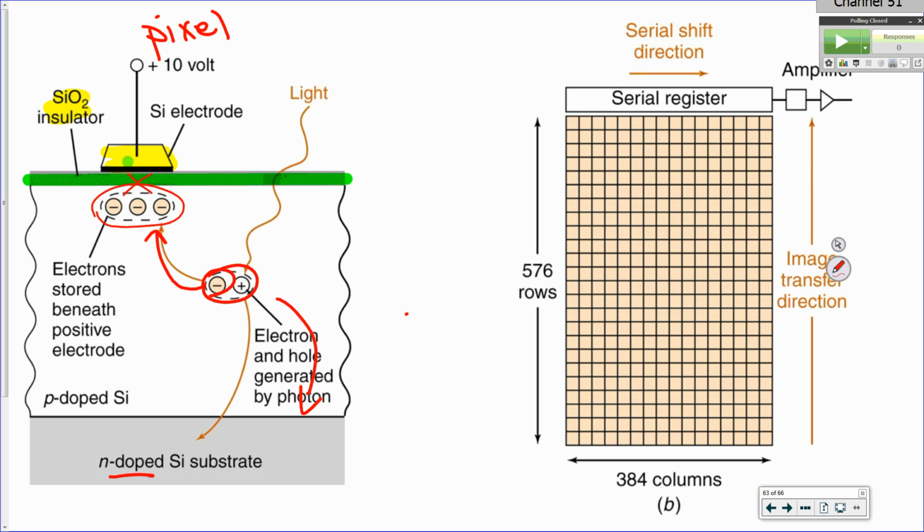All right? Or if that's not enough, if I can track good enough, I'll tell it to look at it for 30 minutes. All right, it's limited by how well I can track the stars. But what happens is, if you think about it in a two-dimensional array, every one of these is going to have a certain number of charges trapped in these wells, right? We can create an image. To detect them is the crazy thing.